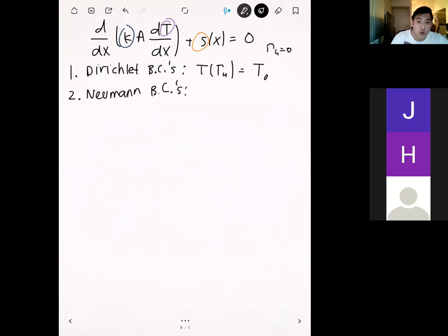And so we also have our Neumann boundary conditions. The way that we denote that is the following. We take the dot product of the normal vector times k dT dx, and the location for this is x equal to gamma h. This can be minus q bar. And this n dot right here, all this does is change the sign depending on what surface you're on.